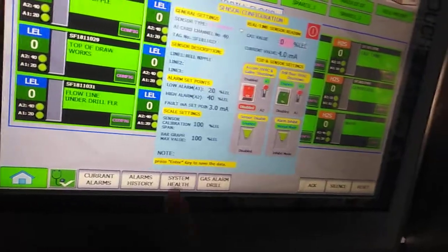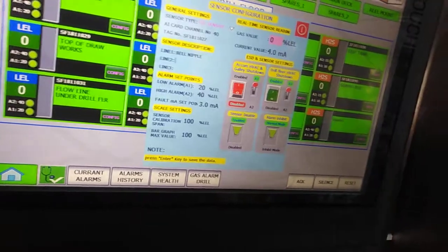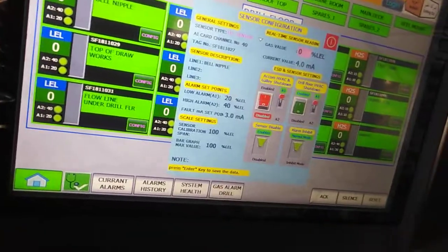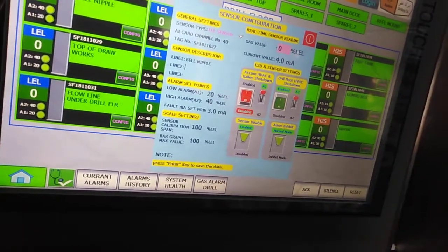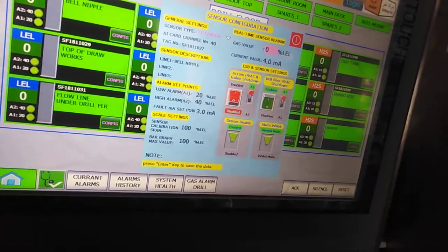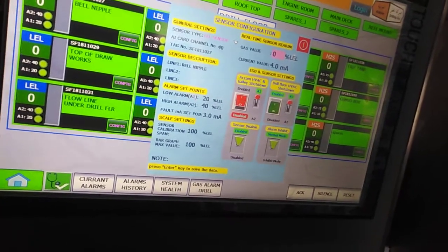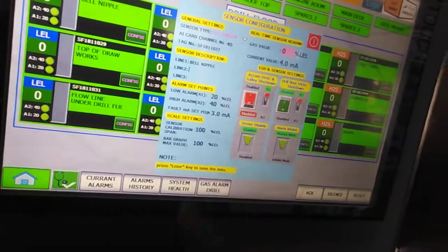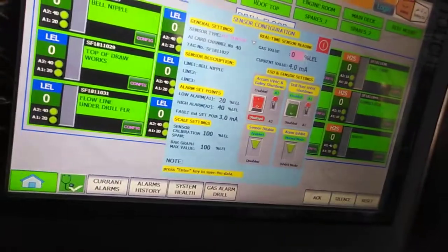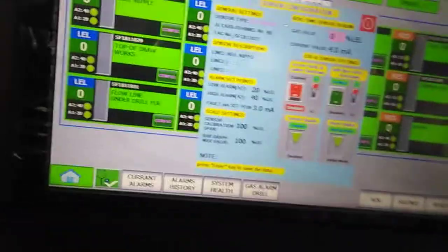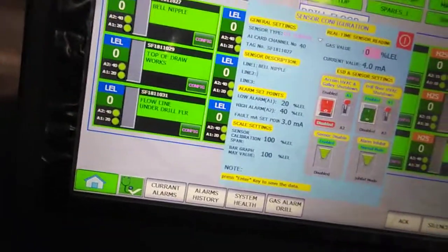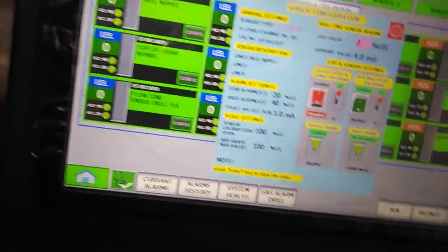And this is the sensor calibration span. When a sensor has a span, we can measure this one, so we can vary it. Some sensors have a 100% span. Some other sensors have a 50% span, like 50% LEL. So that we can select. It means that any type of sensor can be added to this system, either a 50% type sensor or a 100 percent type sensor.